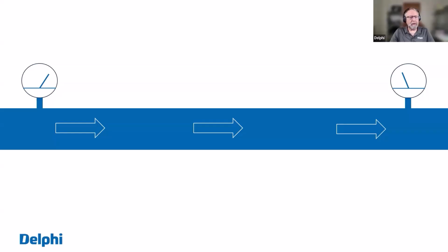And what's happening here, as the water is flowing, there's resistance to flow that takes place, which could be in the walls of the pipe. The molecules of the liquid itself are rubbing against each other, creating its own hydraulic resistance. Consequently, there's an energy loss that takes place. And that means that you're going to have a higher pressure here, and that pressure is going to decrease as you go further down the pipe. Thus, the need for lift stations sometimes in long pipeline runs and things like that.